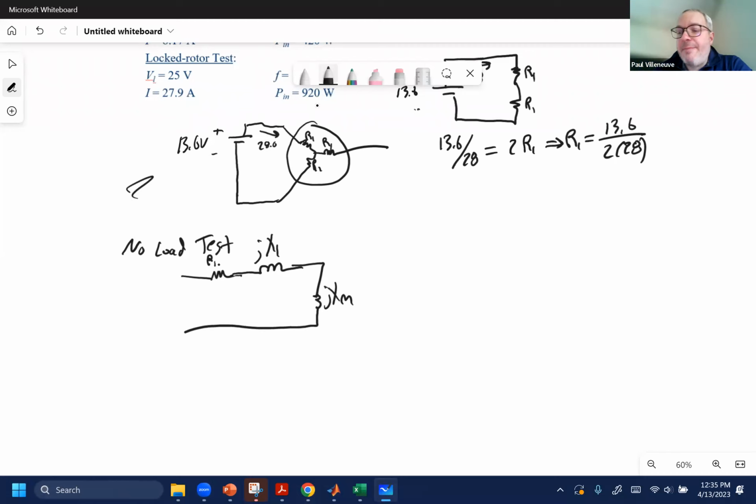So now I'm going to add my elements. I have plus to minus 208 divided by the square root of 3 at an angle of 0, because that's what I know. Remember, magnitude and angle for current and voltage. My current is 8.17, and the angle at this point is a question mark because I don't have enough information to give that.